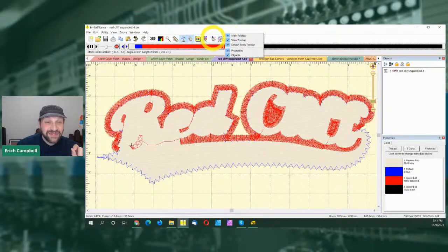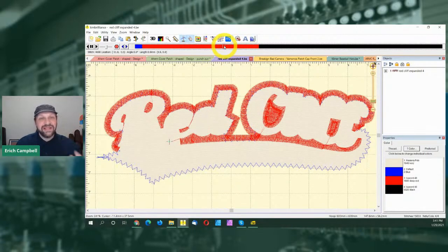Now, I'm going to say this sequence is a little weird. What I'm going to tell you is that this particular piece of felt applique on this unstructured hat, I had to do some really non-standard stuff to keep it from shifting in the hoop the way you'd want to do. Usually, I would be bottom up, center out on everything. This particular applique hat on this machine, I'm telling you, it acted very strangely. We had a lot of waves and ripples, and I was getting some registration errors. And I changed the way I was running it to kind of combat the movement I saw on the machine. Not a standard look. So admittedly, there's some stuff there to look at.